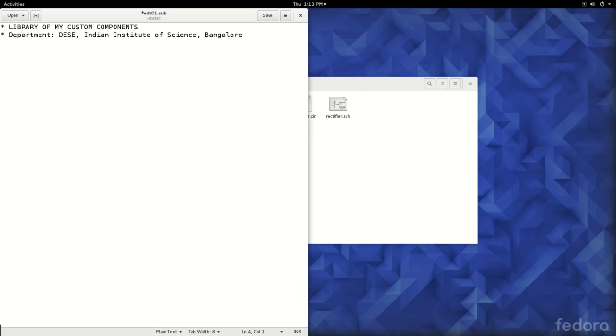What is it that we need to provide a model for? We used a diode there, and it was a power diode. Let us have a model for that. So the power diode consists of 2 parts: a model for the default diode, and a subcircuit model for the power diode. So I will just write this. I think you know how to use Spice and how to make subcircuits. I will not right now teach how to go about making subcircuits, because it is outside the scope of this course. So I assume that you know Spice modeling.